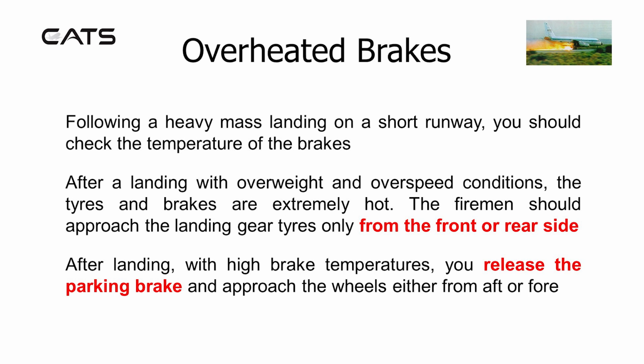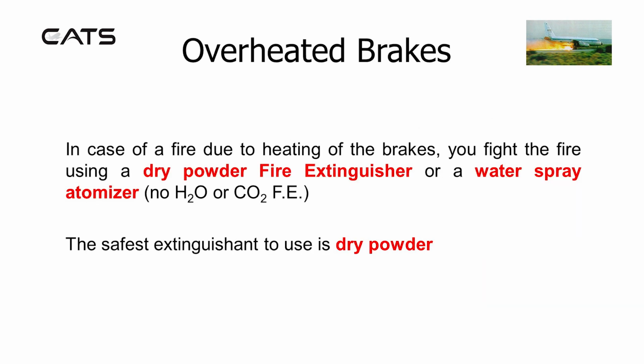The firemen should approach the landing gear tyres only from the front or rear side. After landing with high brake temperatures, you should release the parking brake and approach the wheels either from aft or fore. In the case of a fire due to heating of the brakes, you should fight the fire using a dry powder fire extinguisher or a water spray atomizer if available. The safest extinguishant to use is dry powder.